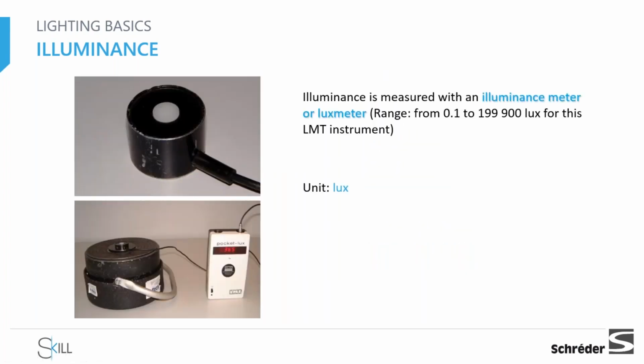For the unit of measurement, we will have a very simple unit. We might even use our mobiles. Here, there's a question about the accuracy of that, but we can have a sensor and then it will measure the amount of light falling on that surface. You see that it's very simple. Normally for street lighting, we will have some device like this, just in case we have a ramp, to make sure that the slope is balanced and the sensor will be horizontal, or parallel to the sea level.